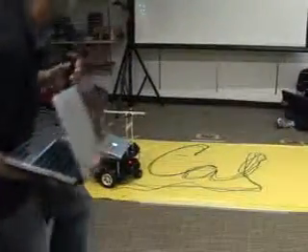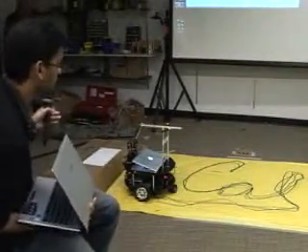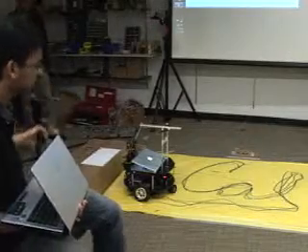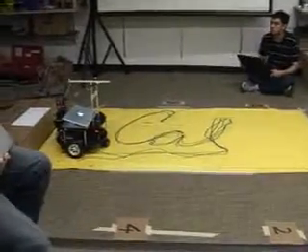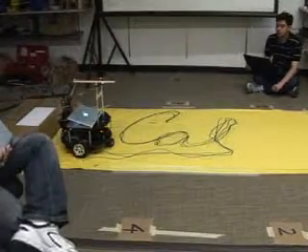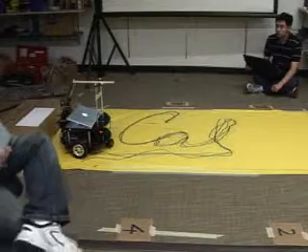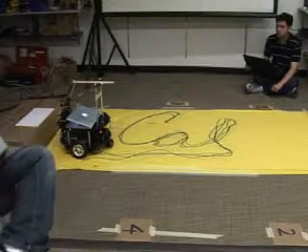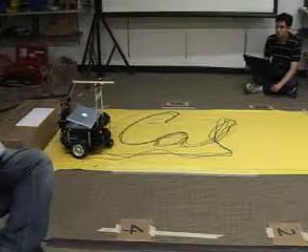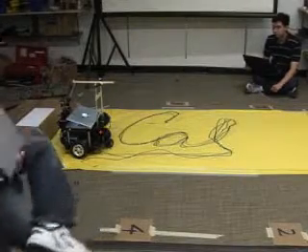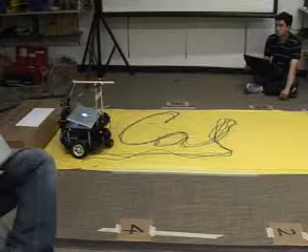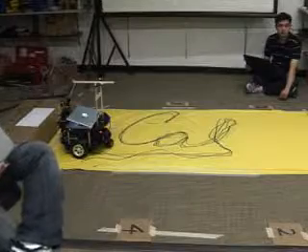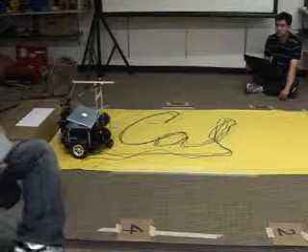So in the path planning, the first priority is least distance. As you can see from here, chef's table, 1, 2, 4, chef's table is equivalent to chef's table, 4, 2, 1, chef's table. So the additional optimization, I should say, comes after that. Since we have these 2 equal optimal paths, the robot will consider the one with the least order infractions. Even though table 1 ordered first, tables 2 and 4 ordered soon after. So the priority goes to servicing 4 and 2 before 1, which is why it chose to go 4, 2, 1 and not 1, 2, 4.